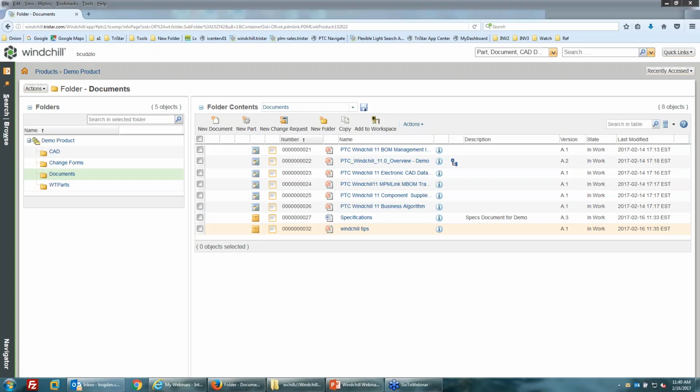This allows you to create the watermark and show it in Creo View. So when you're opening a document, like a CAD document or a PDF, or a CAD drawing plot file, you can see the watermark on top of it, but only inside Creo View. As soon as you export out that PDF, download it, the watermark is not in there.